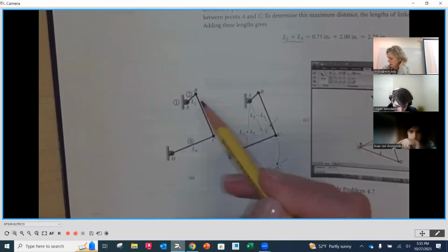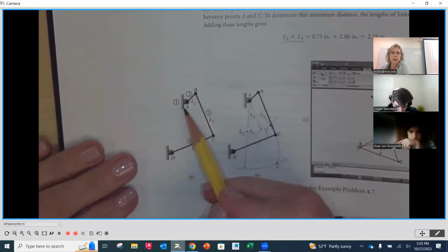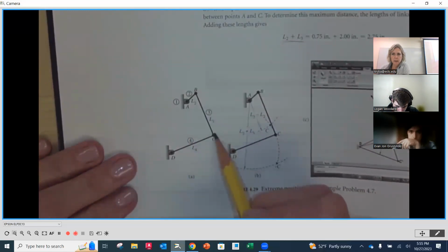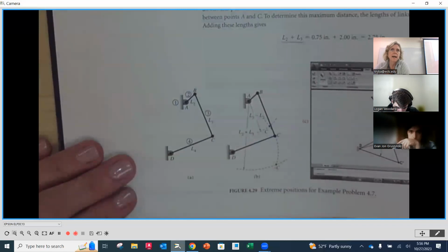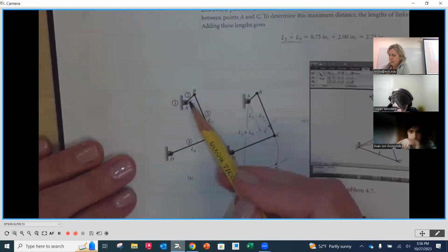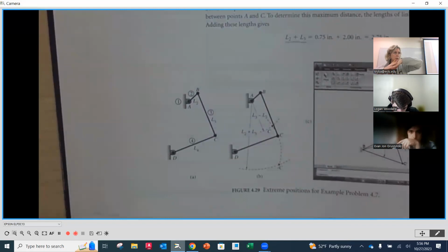So right here, we have a standard 4-bar mechanism. Here's our motor, the center of our motor, our crank, connecting rod, link number 3. And then link number 4 is going to be that nozzle. The nozzle is out here a little bit. If you wanted to add an extra point of interest, you certainly could. I think that would be called for, but in this case, they didn't. And then they're going to do that very same construction to find the furthest extreme position. They're going to add these two together so that they're in line with one another.